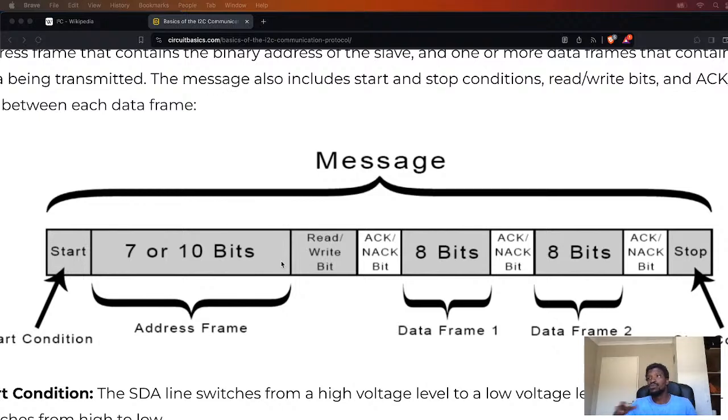And once you know what those bits mean, it's almost like reading commands. So the standard packet of information in I2C would look like this. Whichever device generates the start condition, this here, is going to be regarded as a master.